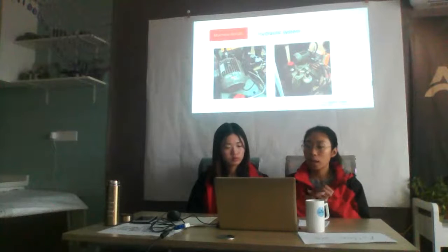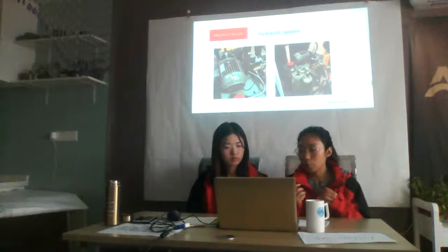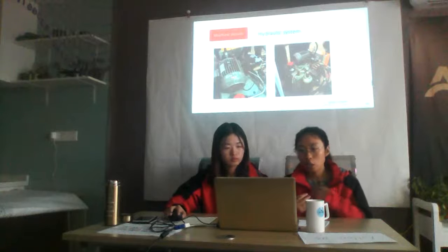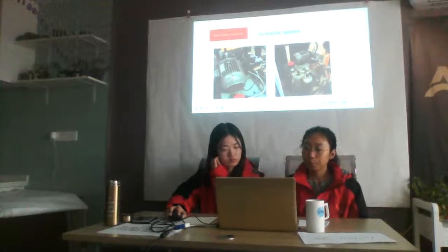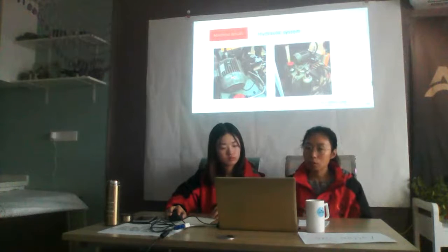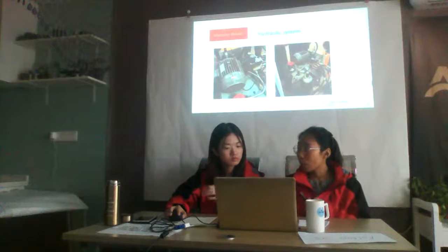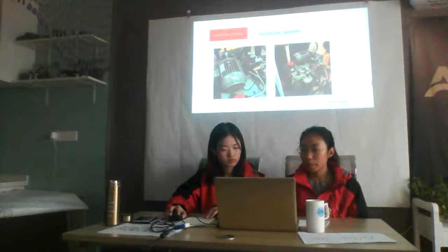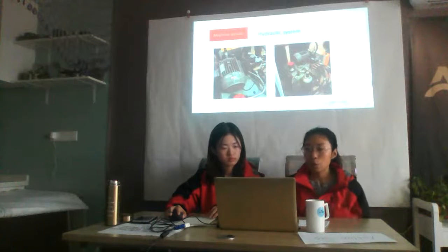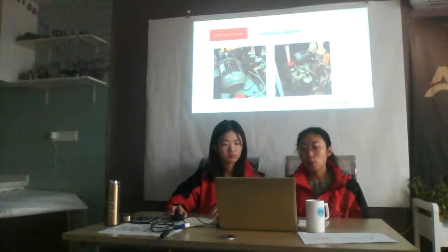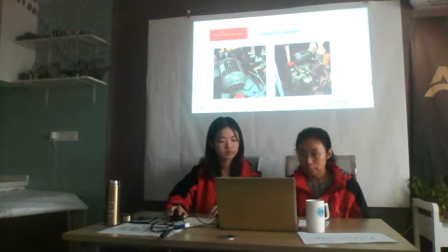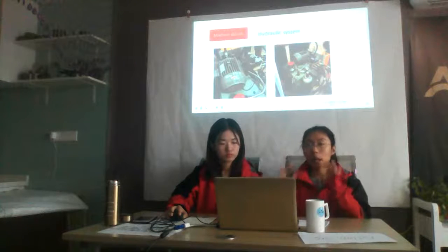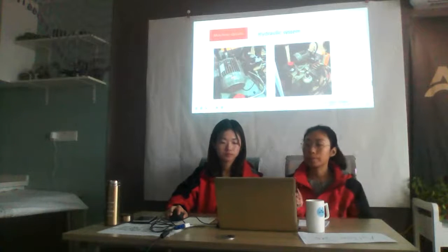And the high-speed CNC plate drilling machine needs the hydraulic station for the hydraulic work table to clamp the workpiece to achieve the processing. So the hydraulic station is also important for the CNC plate drilling machine, but it has some different functions.